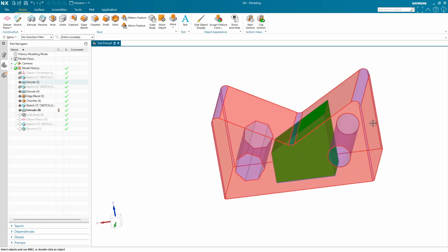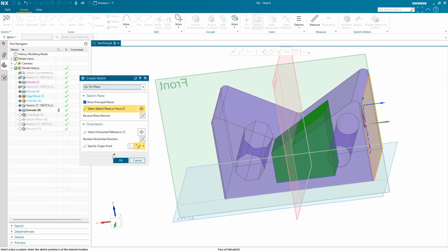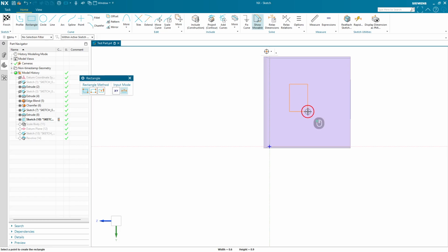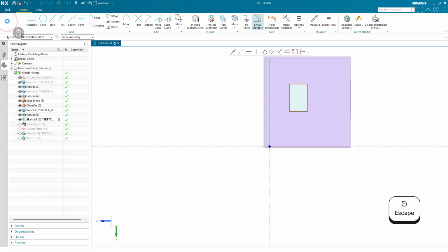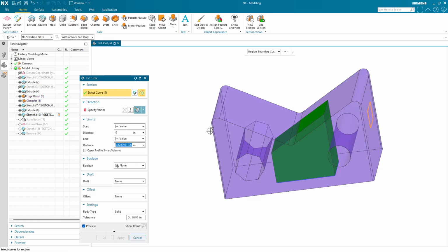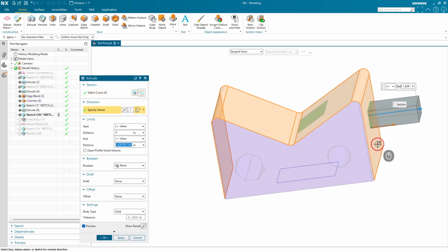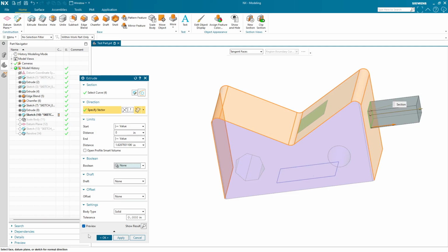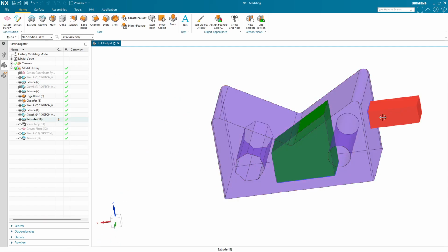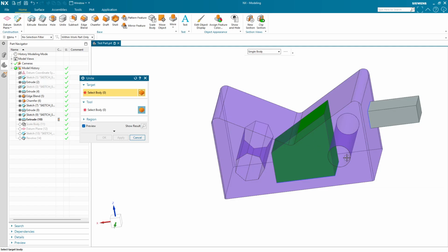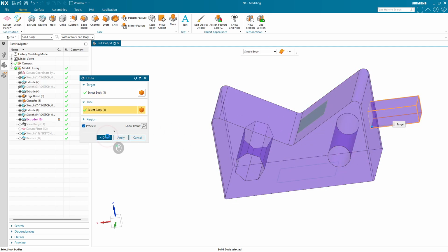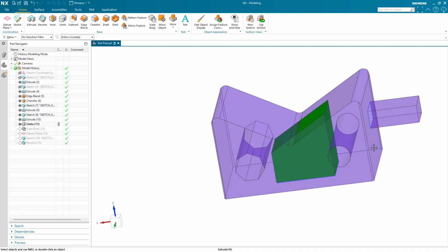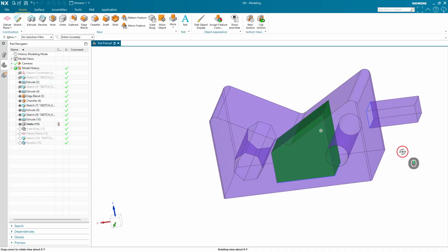Let's say this is sticking off the edge as its own body. You can come in here. Let me extrude that really quick. We're going to do none. Oops. So these are two independent bodies, but if I unite them, we see that this has merged into that because it adopted the purple.